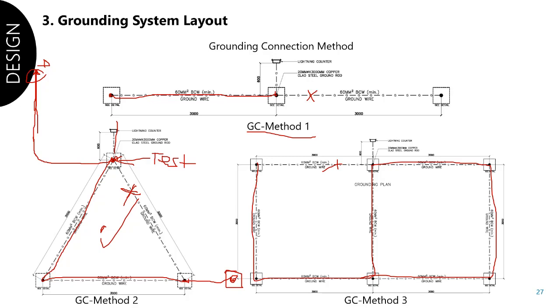So our ground testing, if they inject a voltage, specifically the fall of potential method, right? The fall of potential method. And if it is a ground clamp, I don't know if they have already studied it, but I think it could not affect. But if you do a fall of potential test, of course you inject it, and also include your down conductor in your test. That's why for me, or in practice, you should have an isolation.